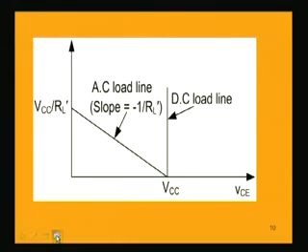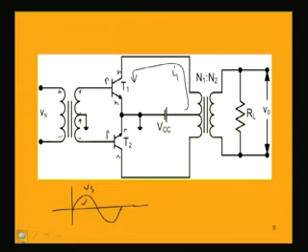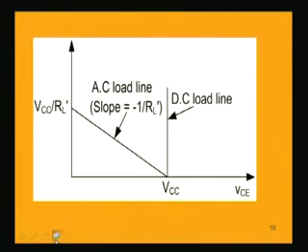That is, in the load line characteristic, if we see the DC load line, as we have earlier mentioned, it will be almost vertical, and that is because the primary windings are assumed to be ideal, having no parasitic resistance, and that is why in the DC condition the current will be infinitely high, and that is why we are showing it by a DC load line, by a vertical line, and its voltage is VCC, the DC voltage, because the source is the VCC source.